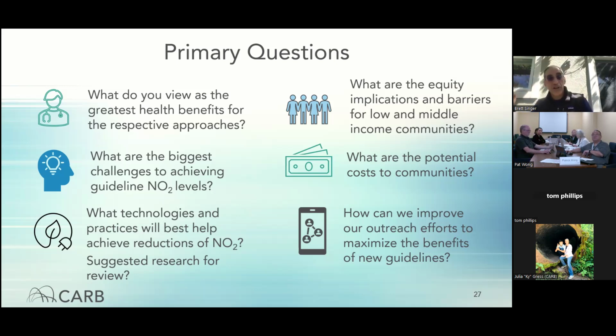And even though there was some discussion earlier about how you're not trying to reduce PM 2.5 from gas stoves, or from cooking, when you ventilate a gas cooking appliance, you are also ventilating all the contaminants that get produced from cooking and also the ultrafine particles and the moisture that's produced from the gas burner. So there are all these commensurate benefits that go along with it. I think highlighting that is really valuable, right? Saying, hey, in general, it's good to ventilate when you're cooking. If you have gas, it's even more important, right? But if you don't have gas, you should still do it.